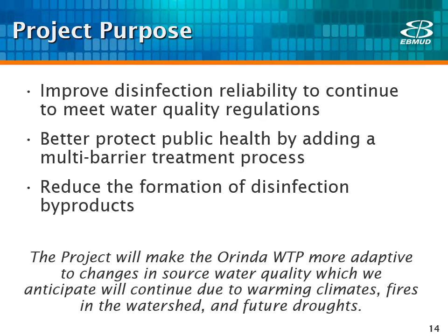The purpose of the project is to improve disinfection reliability, to continue to meet water quality regulations, to better protect public health by adding a multi-barrier treatment process, in this case, ultraviolet or UV and chlorine disinfection, and to reduce the formation of disinfection byproducts such as trihalomethanes.